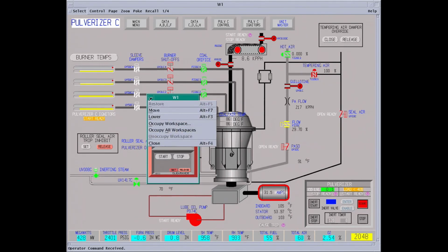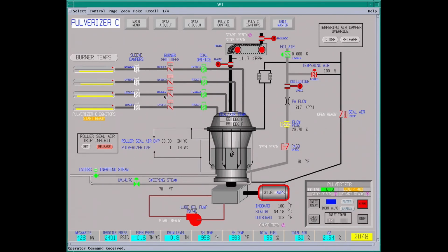A bunch of low flame alarms just came in. This is set to ramp up to about 30,000 pounds an hour. For startup, you can go 20,000. Okay, so this is 1,000 pounds an hour it's feeding in.